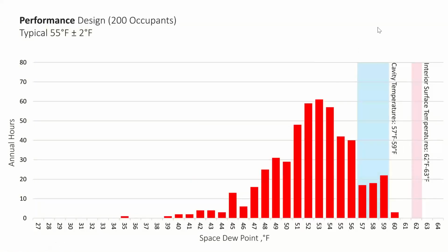That can then be correlated back to those hours of wetting, or how many annual hours there are that may be below the dew point, and that gives them an assessment of how risky this system would be for reducing mechanical ventilation to take away that moisture. So in the end, I believe this project decided that it wasn't feasible, and trying to do some sort of desiccant layer or something like that wouldn't quite meet the requirements, and it'd be a little bit too much on the maintenance side. So they just had to go with that mechanical venting.